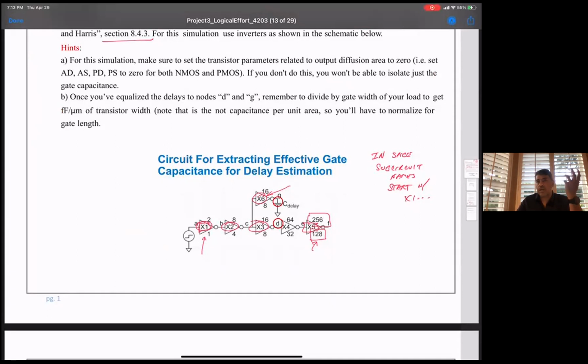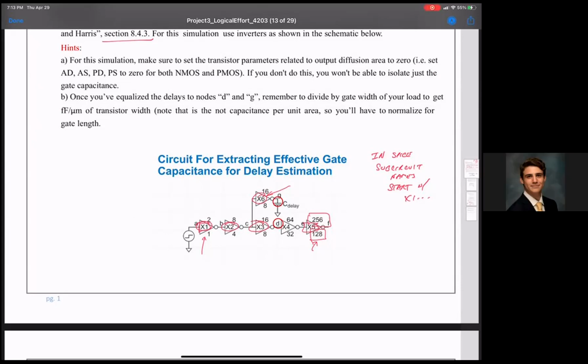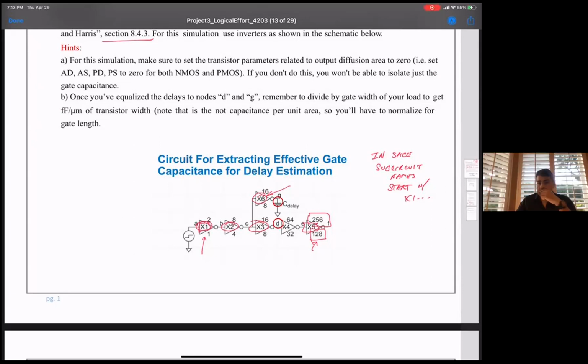I don't think I've used the standard inverter out of LTspice, so I don't know how it picks its transistor models and transistor sizes. It's probably just better to use the actual transistors then. Yeah, I would just use an actual transistor.